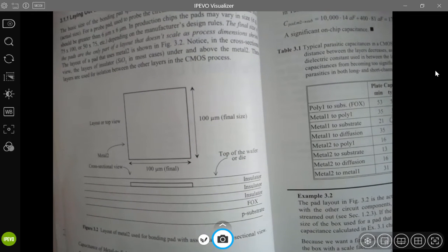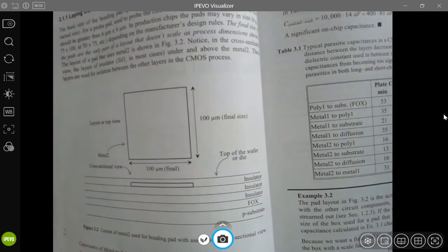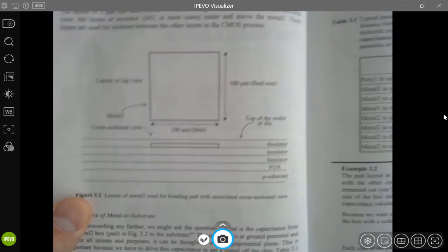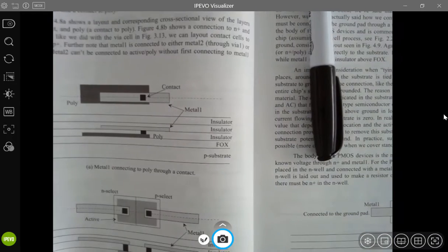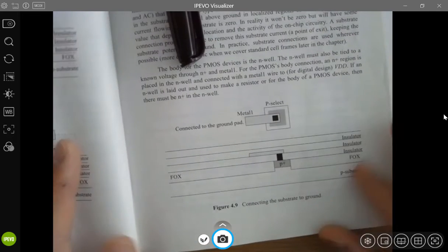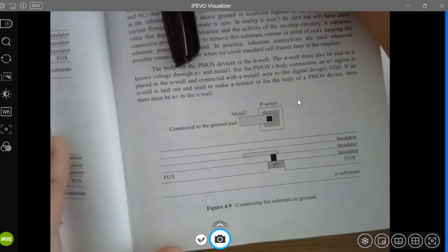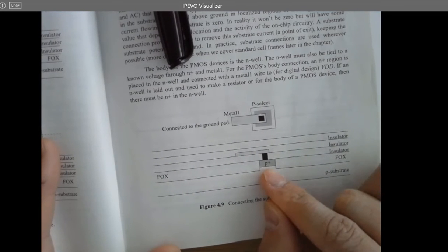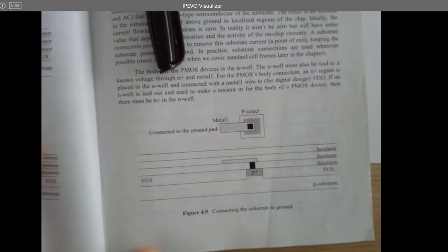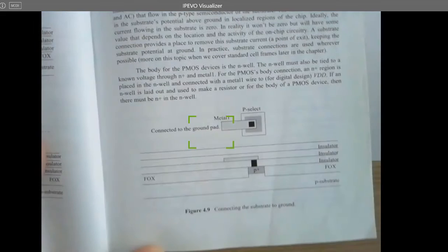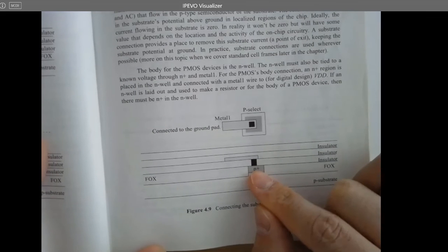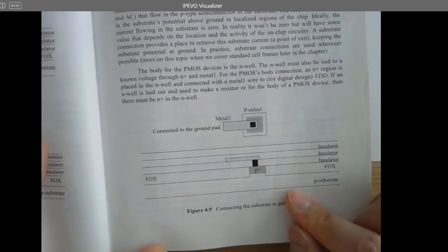Alright, guys. So a few things to clarify first, because this can be a little bit confusing. You have seen all the pictures like something like this, where it labels a Fox layer at a different location. So see here in this picture, the Fox layer is at the same layer with the P+. If you go back, here's a P substrate, and then Fox, there's the opening, has a P+ over here. So this is not an accurate figure actually.